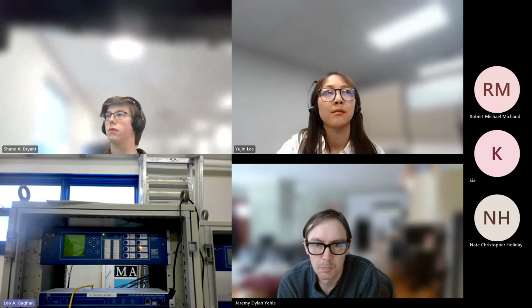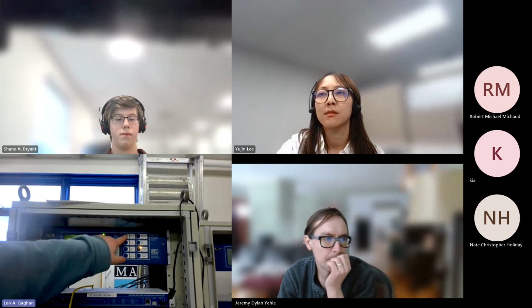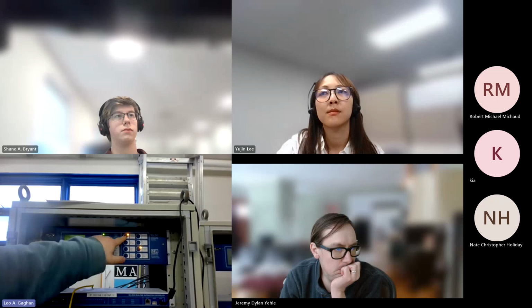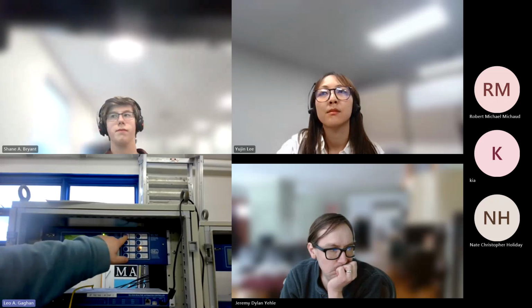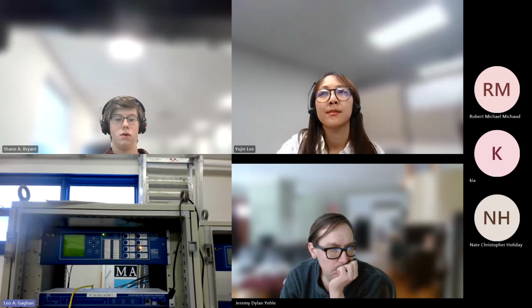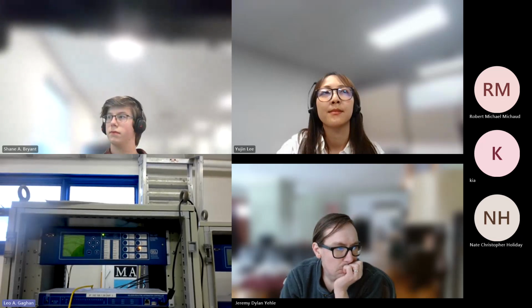So basically what this logic does is it changes our permissions to open and close that breaker. When I put this in 52 control switch enabled, that means I can open and close this breaker from the control switch down here. When it's in relay, that means I push this push button up here. So right now it looks like it's in relay. With it in relay, it doesn't do anything, right? But I put it into 52 control, I had to hold that for a full second, and I can turn this on and off. That toggle. Well, with that, we've just verified that logic, right? We're able to toggle it on and off. We can come in here, say, okay, that worked.